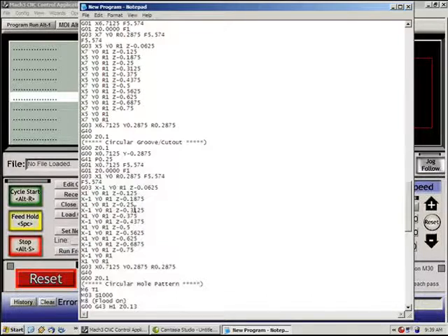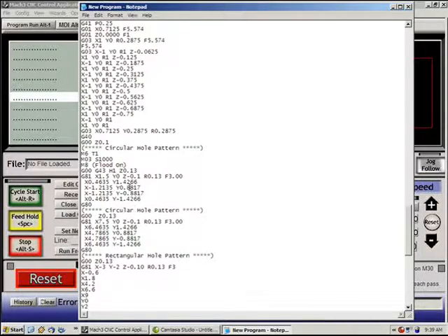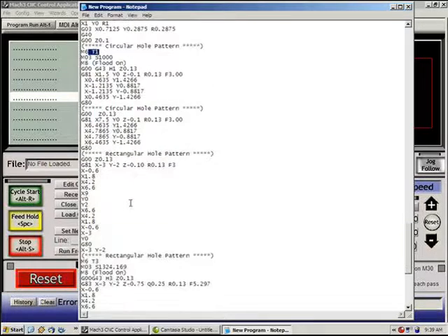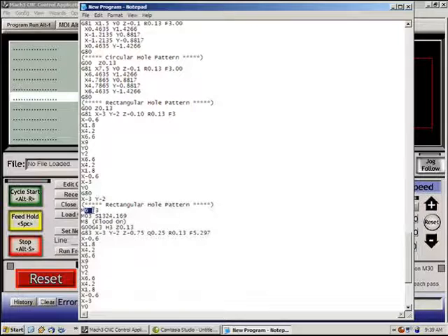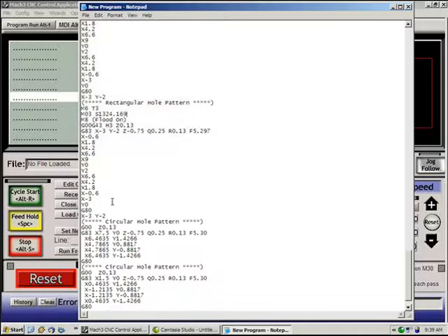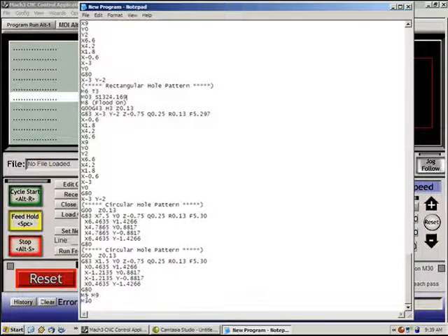We keep going down, and we get into our patterns, and we change to a drill bit. And this drill bit, actually, we set it back to tool 1. This was for our spot drill. Then we get down here, we change it again for tool 3 for drilling with our 375 drill, and then we get to the bottom where it stopped our program. But you'll notice that nothing else was put here. After we got done programming, we actually went through the wizard set and moved around a fair bit, but since we hit cancel, nothing else was appended onto the file.